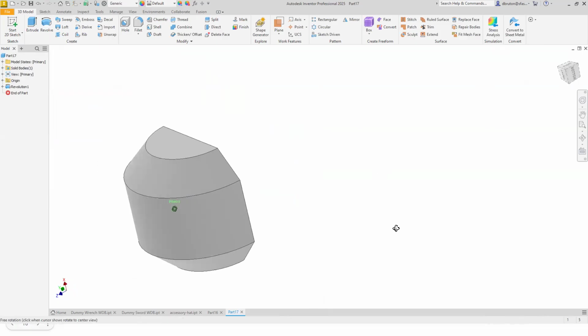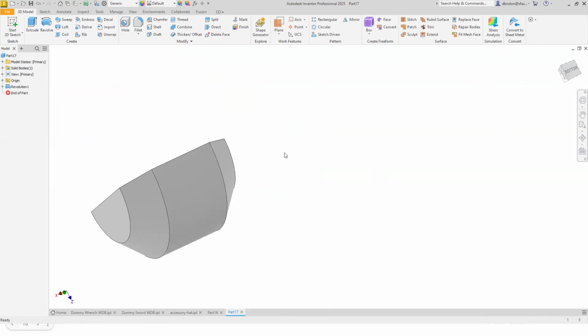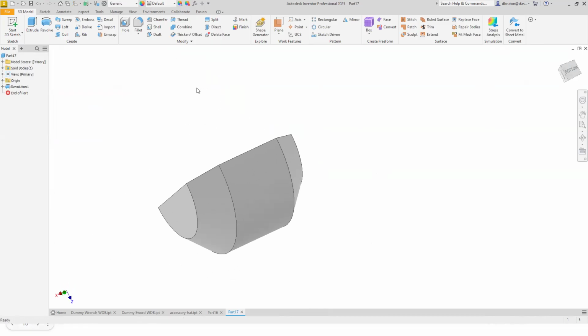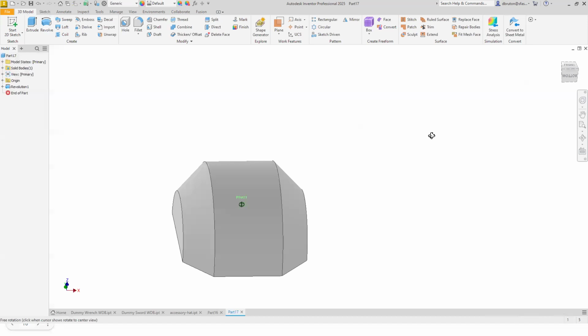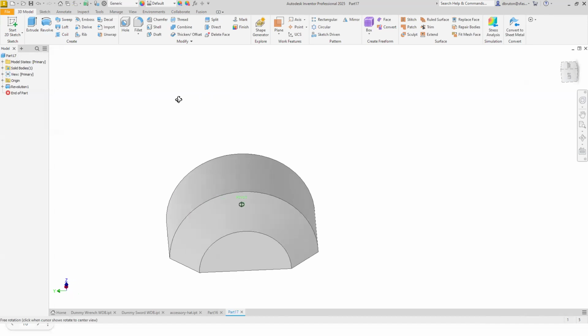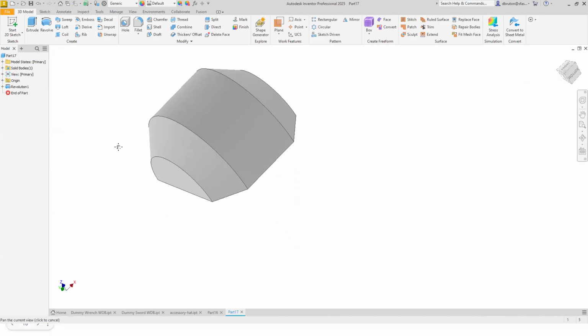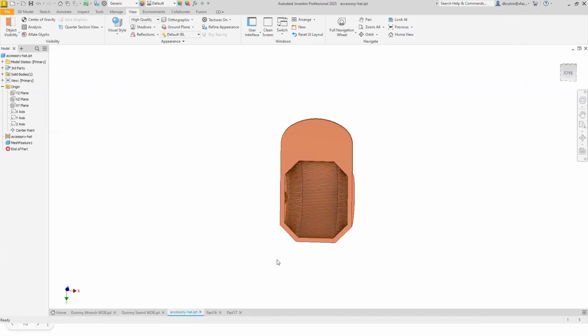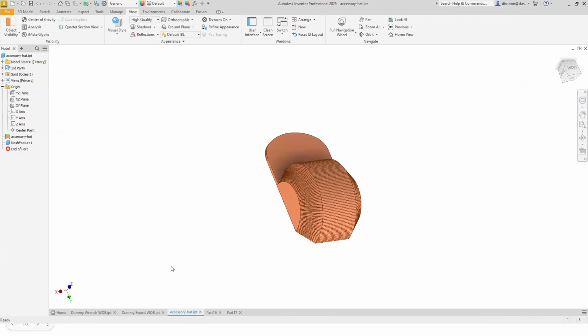Of course, we want to make it more stylish and curvy using fillets, but we're just making one for the crash test dummy. Now, we'd also need a brim on the hat, or I guess we can make it any kind of hat we want. But I'm going to follow the model that we've downloaded here that has the brim that looks like this. So all we need is a closed shape out here on the front that kind of looks like a cat with two ears, actually. And so we need some curvature there and then a closed shape. And we'll extrude that 0.75 like we did before.